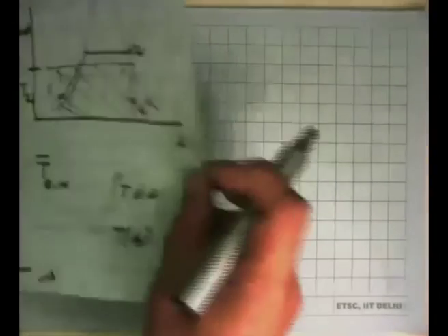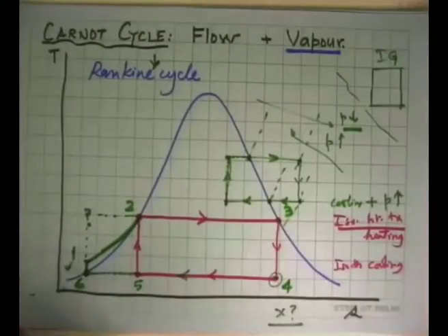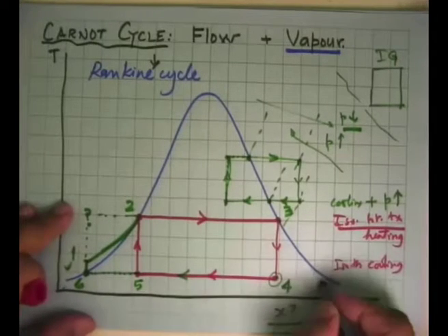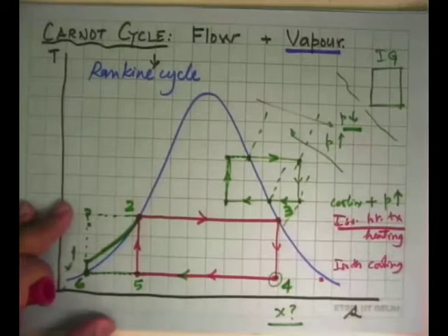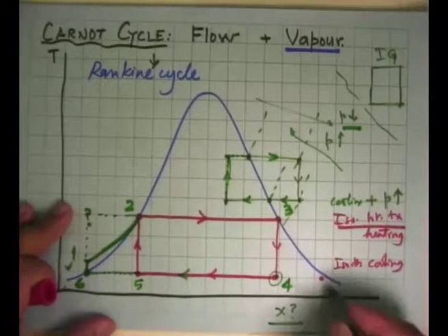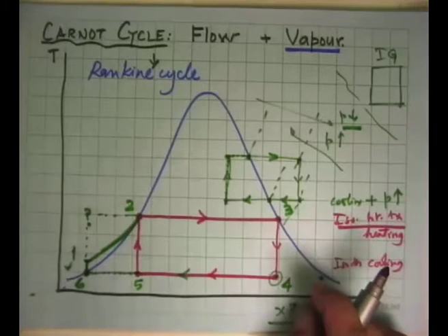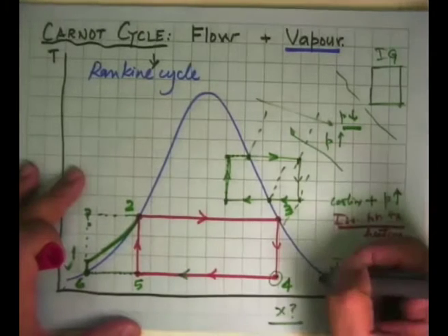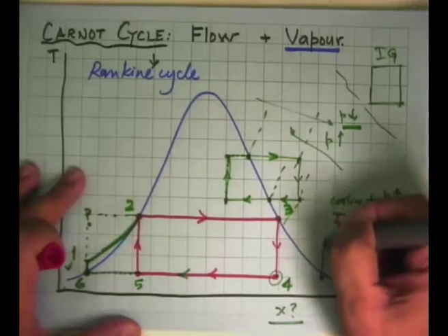And the answer for that is, I'll show it on this diagram. I want to take 0.4 from here to here, very close to 1. That means this is a state at which the steam's expansion in the turbine comes to an end. So the turbine process has to lie on a vertical line which goes up here.